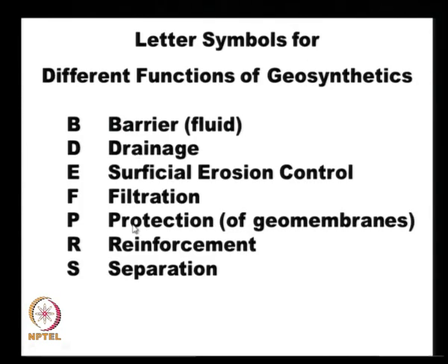Let us go back to the different functions that are given by the International Geosynthetics Society. This we have seen in one of the earlier lectures. These geosynthetics can play an important role in most constructions. They can act as a barrier, and the barrier function is exclusively reserved for geomembranes, and this is one activity where our natural geosynthetics cannot play a role.